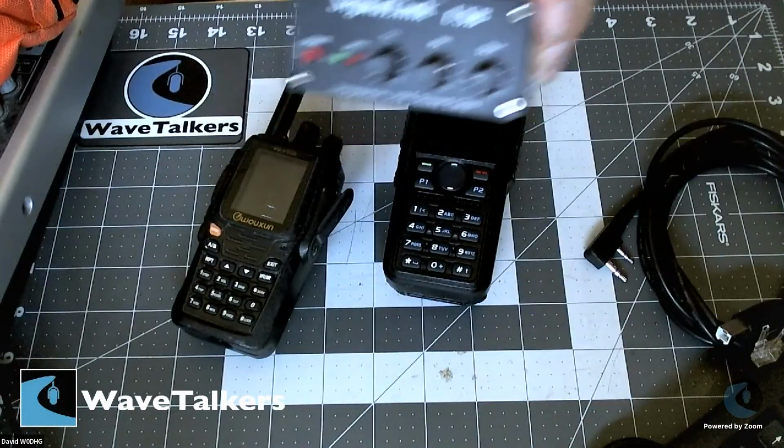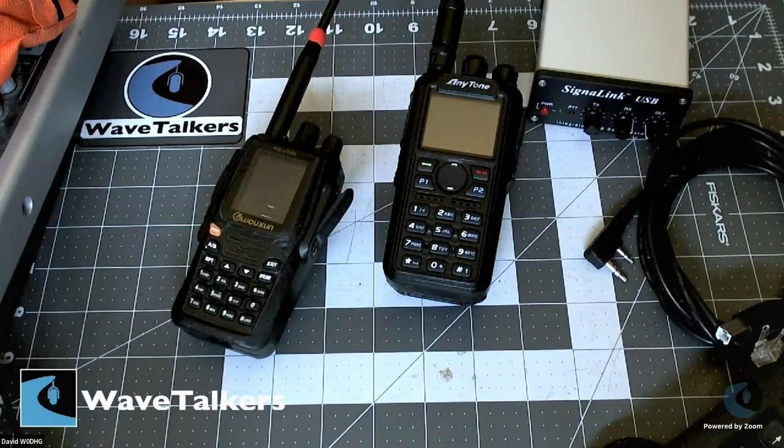There's always the cable plugged into the back of the radio there. It comes out in the center console. When I want to use it, I pull out the SignalLink, I plug it in, I take out my laptop, I use the USB connector, and that's great for when I stop, when I want to use a full 50-watt powered radio, and I can tune the power down on that. And I've got a big battery in there, and it can last a long time, but there may be times where I don't want the truck running. I don't want to drain the battery out.